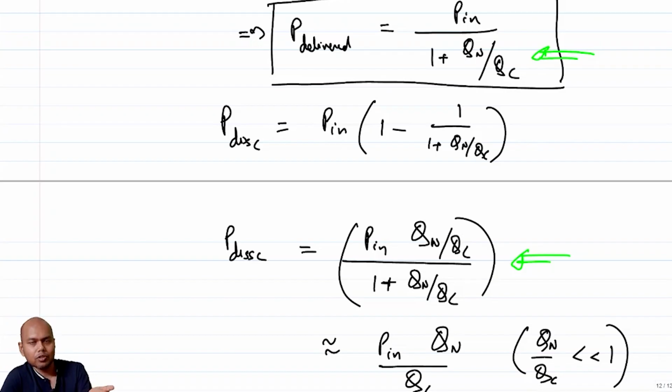In most cases you saw, if you have one L and R, or one C and an R, and you are trying to resonate out the imaginary part, the N was essentially either omega naught L by R or 1 over omega naught CR, which essentially was the Q factor of the network. So your Q factor and the transformation ratio are essentially the same, which means that if you want a large impedance transformation ratio, you end up having a large Q of the network.